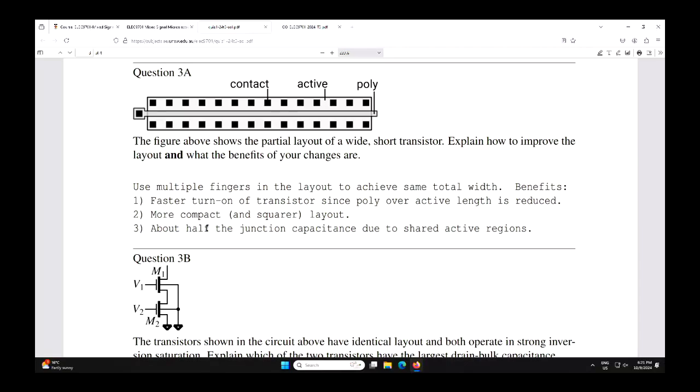But the contacts are different to the metal. There's a different process to get the contacts done. First you've got to etch a hole through the insulator, and then you typically plug it with tungsten or something like that. The insulator protects the rest of the stuff from that.